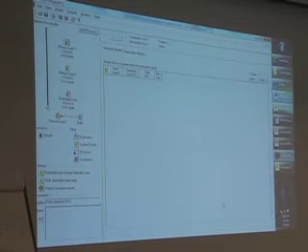So you wanted to be able to do a sensitivity that's not just changing the overall size of the load, but also changing the shape of the load. So you define a shape for the load that's not going to change, you define a separate shape for the load that is going to change, and Homer will just add them together, but because you can do sensitivities on them, you can actually change the shape of the load. So it gives you a little bit of flexibility.